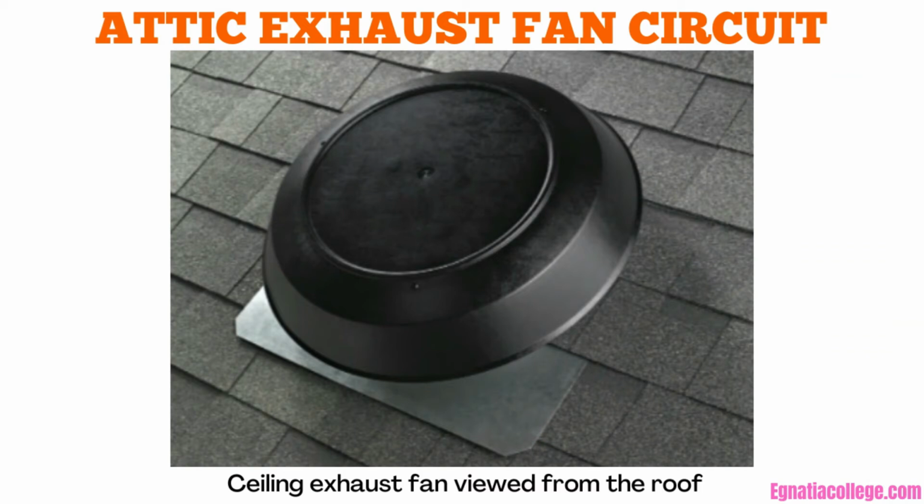On hot days, the air in the attic can reach a temperature of 65 degrees Celsius or more. So it is desirable to provide a means of taking this attic air to the outside. The heat from the attic can radiate through the ceiling into the living areas, raising their temperature and increasing the air conditioning load. Personal discomfort increases as well. These problems are minimized by properly vented attic exhaust fans.